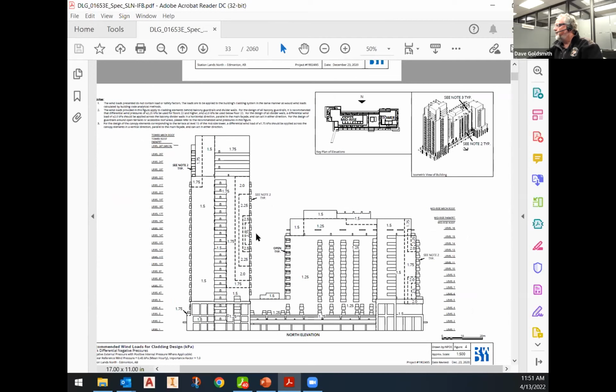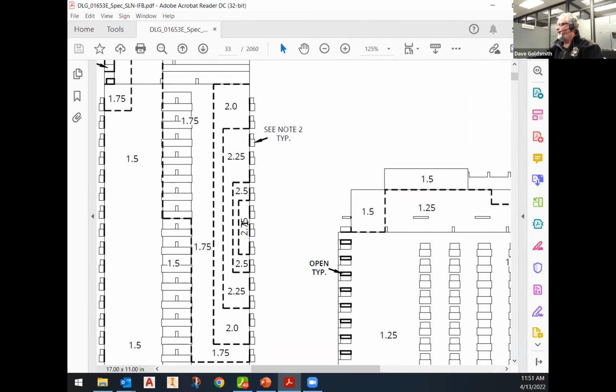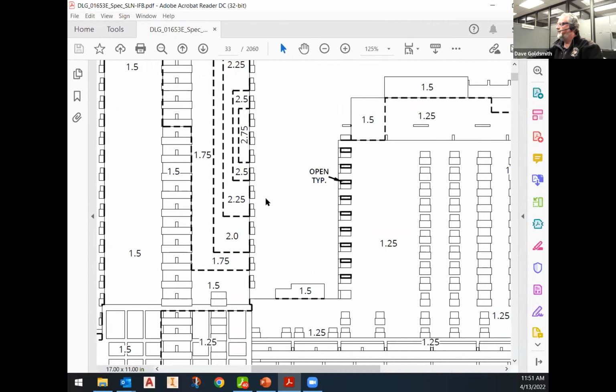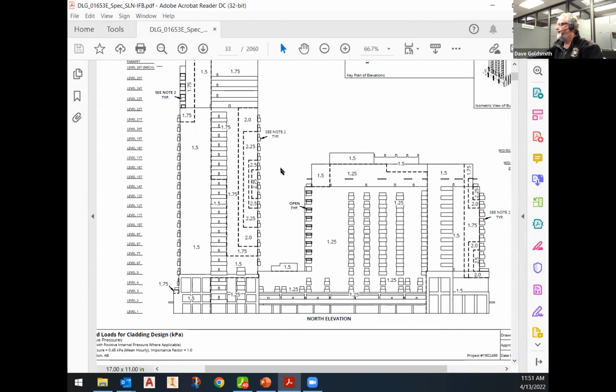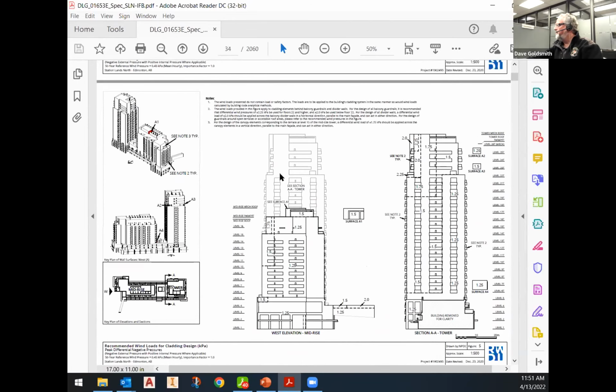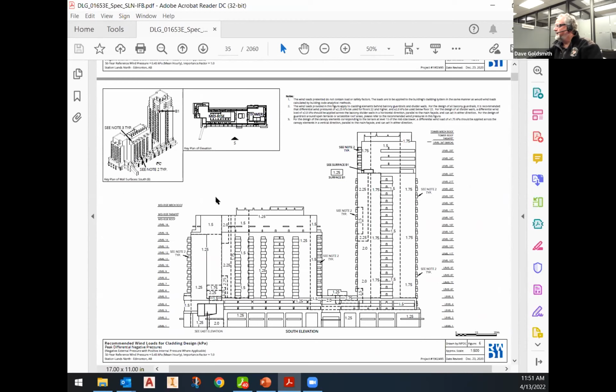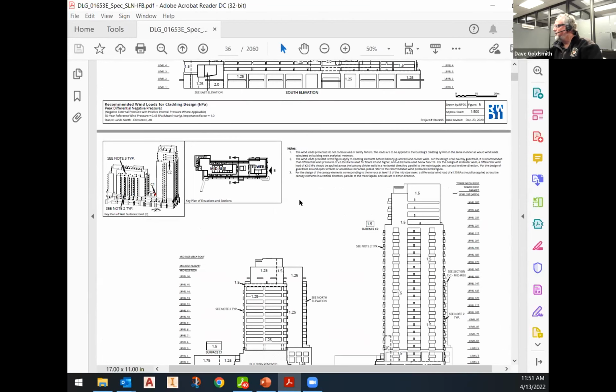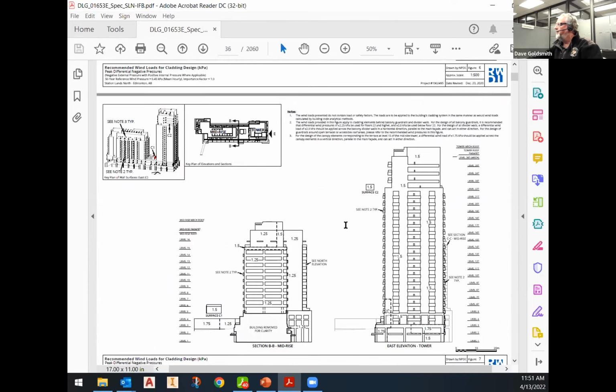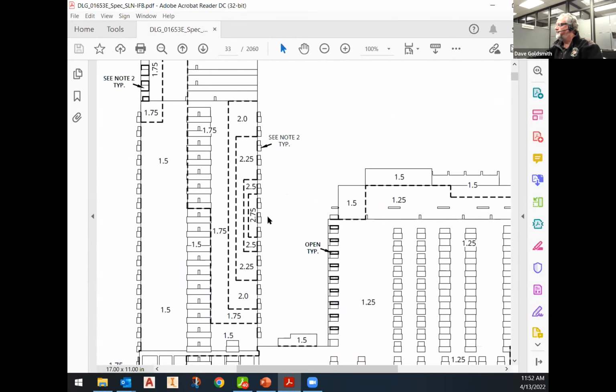So if wind tunnel testing were not being done for this building, probably the structural commentaries would not have come up with pressures that are quite that high for the corner windows that are partway up the side of the building. They did it from all of the different sides, and I went through there and looked for what the maximums were. Here are the maximums from all of the different sides, and that number on the very first illustration was the very highest pressure. And we checked that our glass strength and our mullion deflections in our quote were going to be sufficient to bear those pressures for the windows in that part of the building.